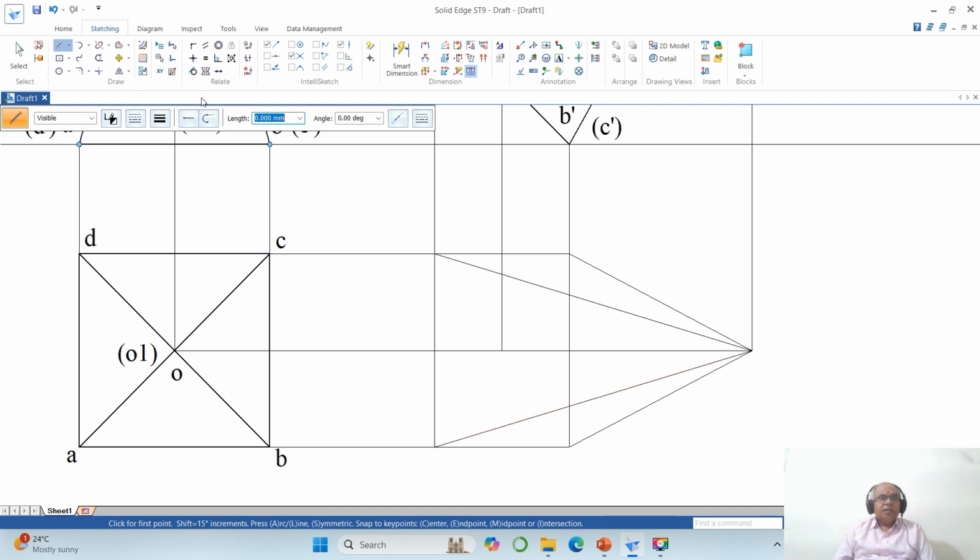Now we need to clear that. So to do that, I will go for split this line till here. Okay. Similarly, you split this line till here. Then you split this line till here. Once you do that, now we are going to start writing the visibility. So first one is all the exterior edges of the boundaries of the solids are visible, then you are going to get it as 0.5.